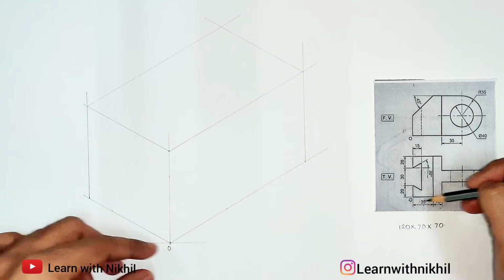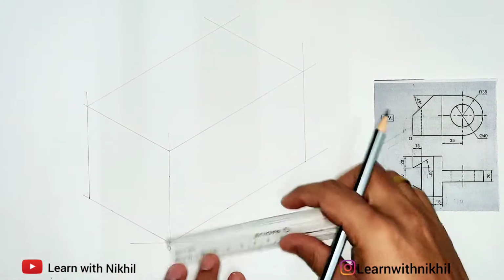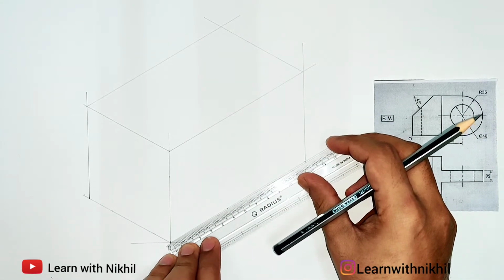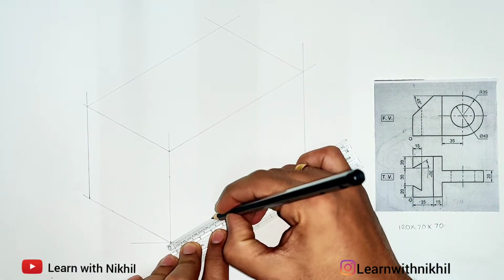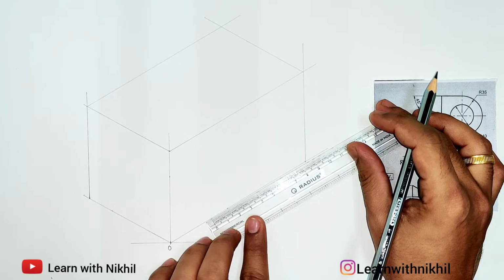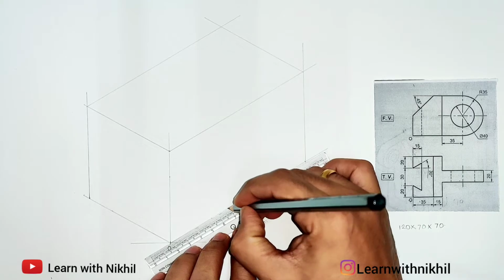We have this angle part, we'll do it later. So first this distance total, this is 35 plus 15, that is 50, and that is a dark line. So this is 35 millimeter, and after 35 millimeter 15 millimeter, so total is 50. Make a dark line here.